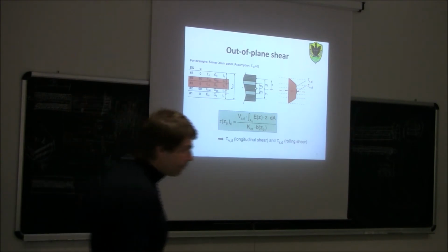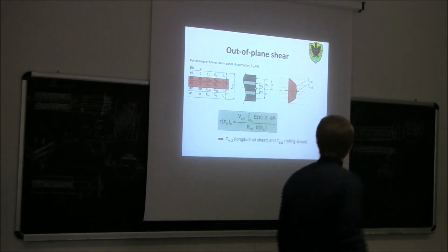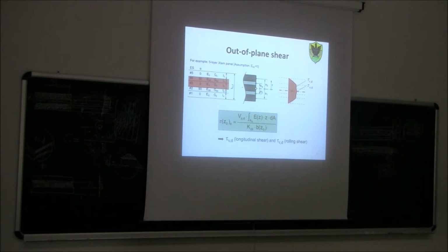Since the wood is basically arranged perpendicular to the grain, in this case, I will have to take the rolling shear. Okay? So here I will have to check for shear, for sure, the inner layer. So shear demand in the inner layer, which is also the maximum shear stress, less than or equal to the rolling shear resistance.